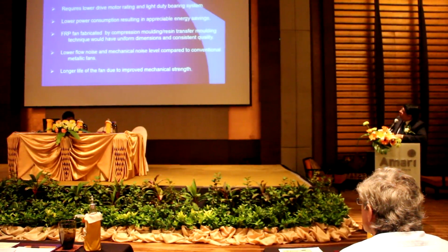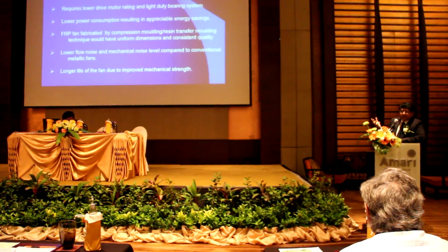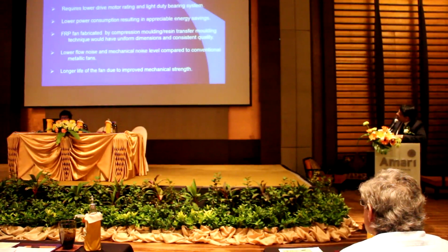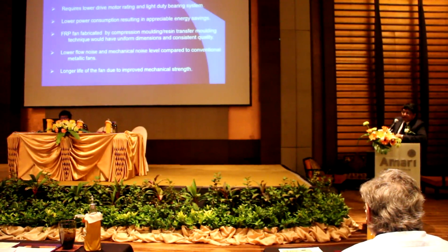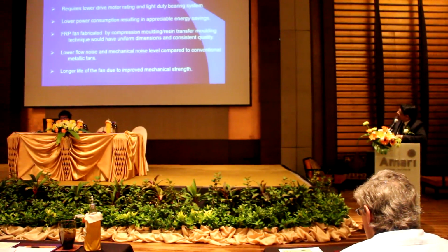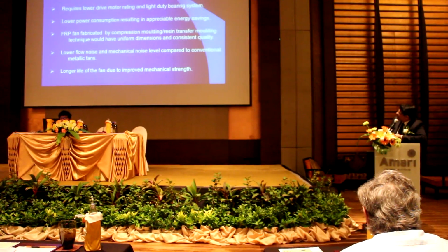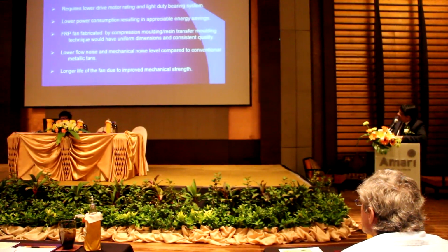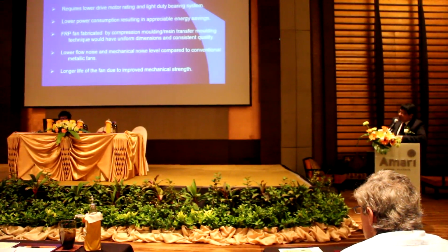Basically what it does is, the mechanical systems, the drive bearings, everything, have a higher life because you are using a lesser load on them. They require lower drive motor rating and light duty bearing system, low power consumption, appreciable energy savings. Compression molding technique we use, resin transfer molding technique, so that they have consistent quality and uniform dimensions. The aerofoils that I use would facilitate low flow noise and mechanical noise level compared to conventional metallic fans, and longer life due to improved mechanical strength.